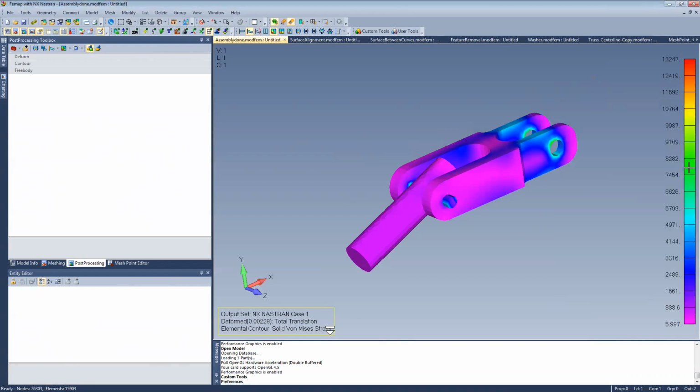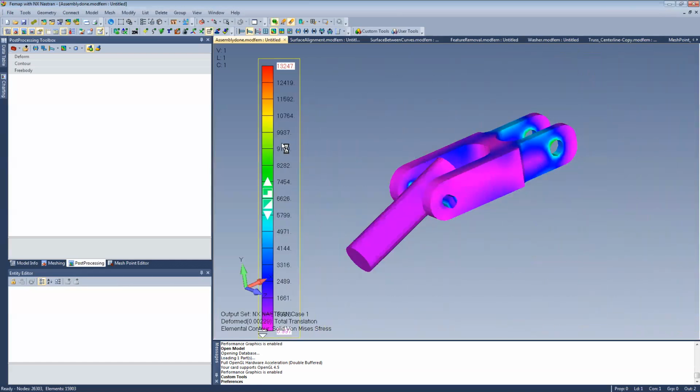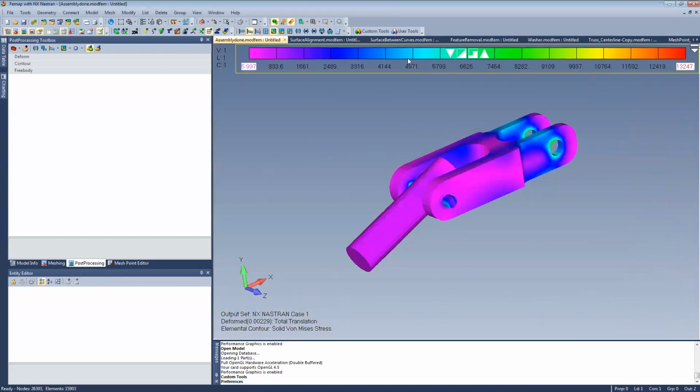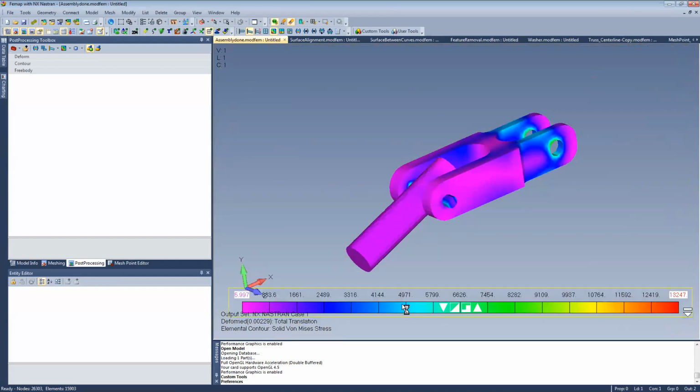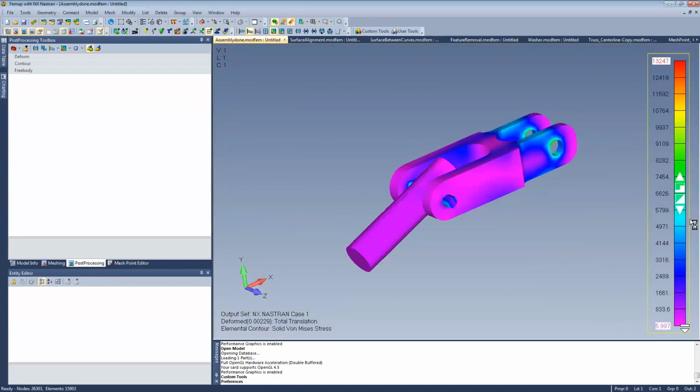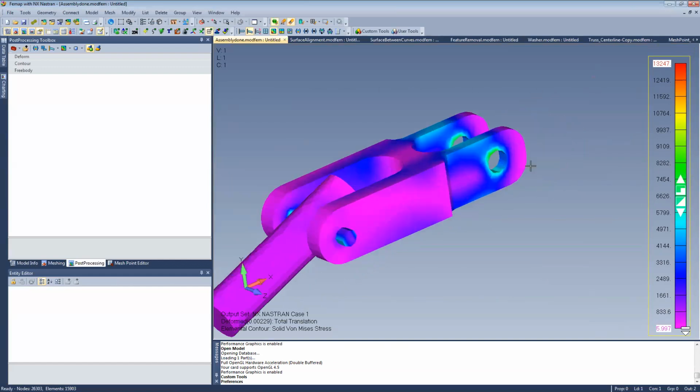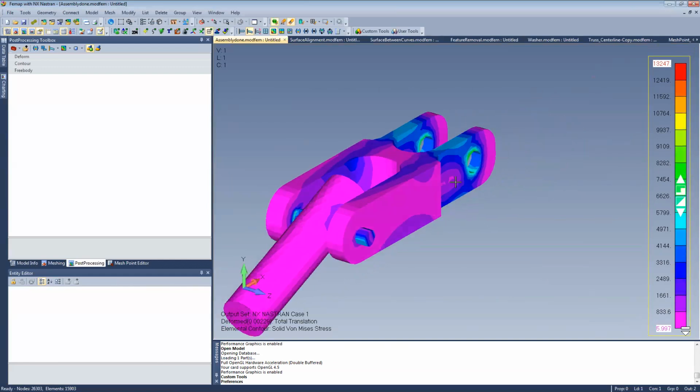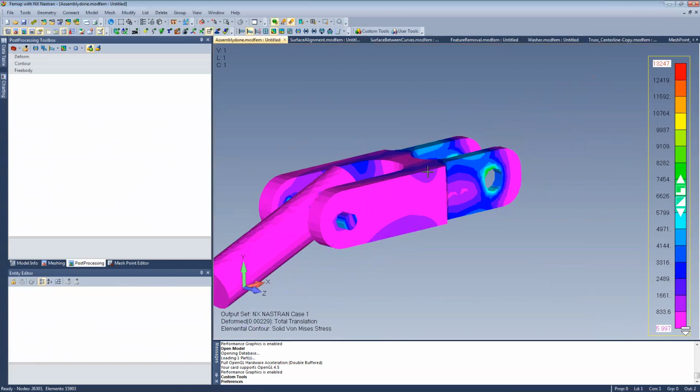If we look at the legend now, when I click on this, again, it's not just hovering, you have to click, and then if I click and hold, then I can start to drag, and it'll intelligently change based on where I'm dragging it to. And there's some other options here as well. So I can pretty easily switch between the level mode, which is smooth right now, but I can change it onto banded if I like that. Sometimes I like that for reports more.